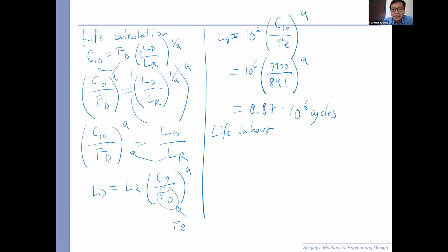What should I do? Any suggestion? How do I do this? Divide by RPM. Okay. And then divide again with 60. Okay. Explain why I divide by RPM. You divide with RPM to get the minutes. And then you just need to convert it to hours.